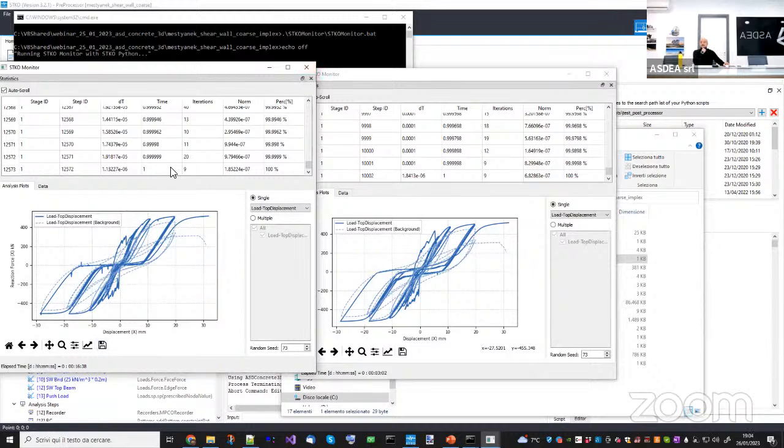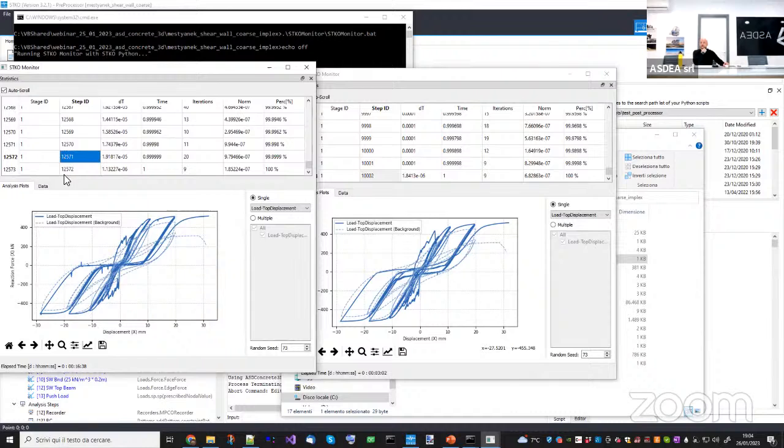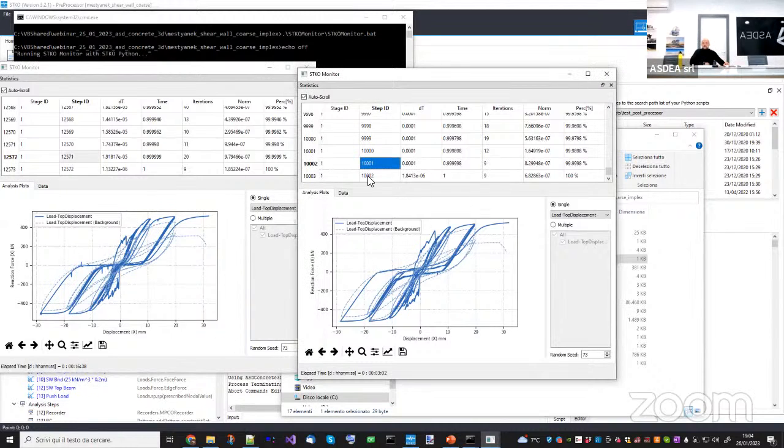This is very important to keep in mind. And the number of steps? Well, here I have precisely 10,000 steps. Here I have a little bit more because, due to the non-convergence of the implicit scheme, I had to use adaptive time step. But pretty much we have about 10,000 steps for just 3 minutes.